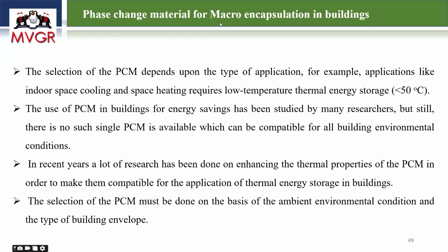So if you want to regulate this temperature, you put the PCM material over the slab. It will absorb the heat during the morning time. The heat that is exposed is absorbed by the PCM material and stored in it. During the night time the climatic conditions are completely different, and you need to release the heat. At that time, the stored heat will be released to the interior part. So you maintain a comfortable condition, and we can avoid dependency on air conditioning systems.